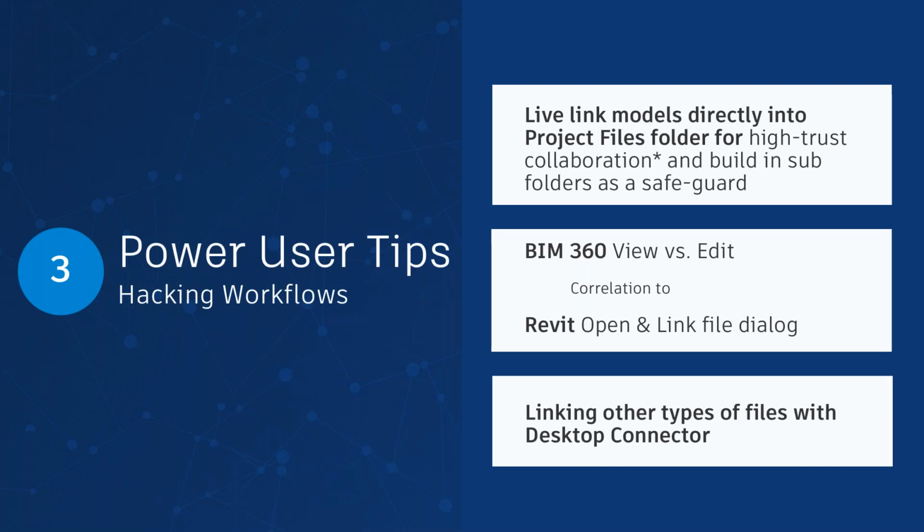There's now, I don't remember the name of the tool, but it allows the civil engineers to publish a topo surface that you can link into Revit from Civil 3D, and that relies on the Desktop Connector application as well. So pay attention to that. Go grab that. It's still relatively new. Still has a ways to go in terms of development, but it's great for what it does even today, and we like it. So we're starting to embrace that and use it some more.